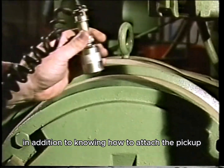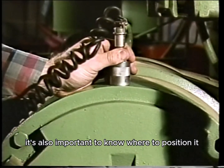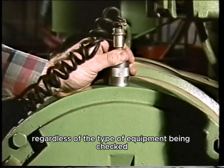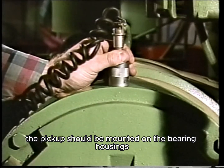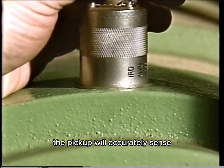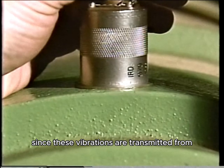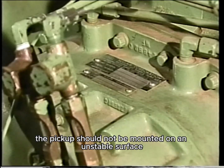In addition to knowing how to attach the pickup, it's also important to know where to position it. A few general rules apply, regardless of the type of equipment being checked. For example, the pickup should be mounted on the bearing housings or bearing caps. This ensures that the pickup will accurately sense the machine's vibrations, since these vibrations are transmitted from the rotating element through the bearings.